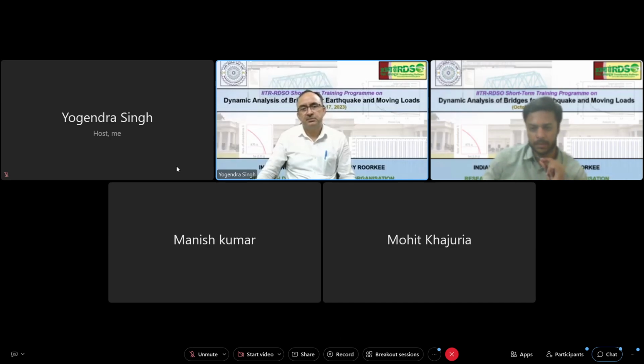Mr. Dharmendra is asking, for a nonlinear dynamic study like IDA, what will I do if a sufficient number of ground motion data are not available at the site? Can I use other ground motion data in case of insufficient ground motion? Actually, you have to use the best ground motions which are available. There is no specific limit defined that the ground motion should be within that range. Whatever is best consistent with your site and source conditions, use those. Make your best effort through all the available websites you can obtain from.